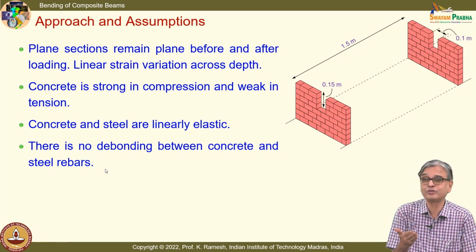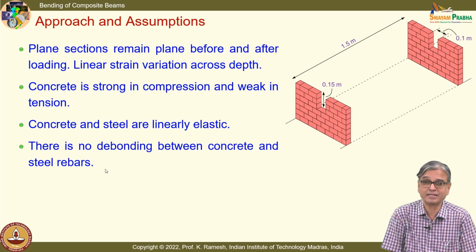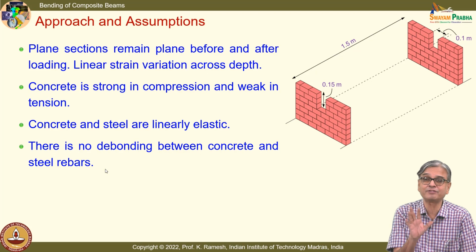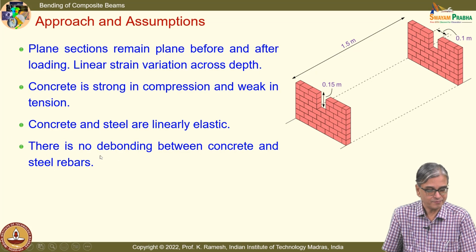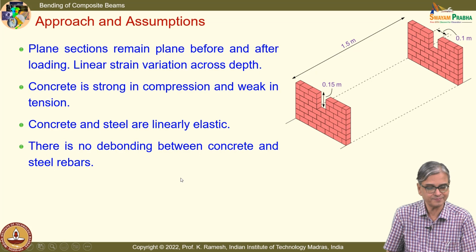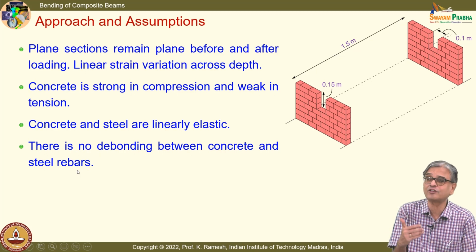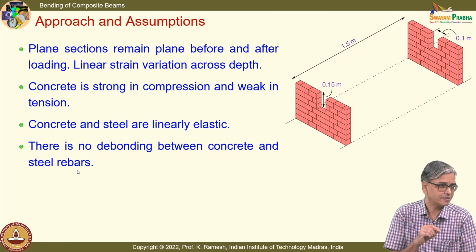See, it may so happen when you construct the beam, it may be like this, but if you have not taken care of water seepage into the system, you may find that steel will corrode and it will increase in volume, and you will have debonding occurs between the steel and the concrete. But now, since we are designing the beam, we are in a comfortable situation. We ask the contractor to make a good beam following all the good manufacturing practices, so that you ensure that the steel rebars are integrated with the concrete. That is a very, very important statement. Okay, there is no debonding.